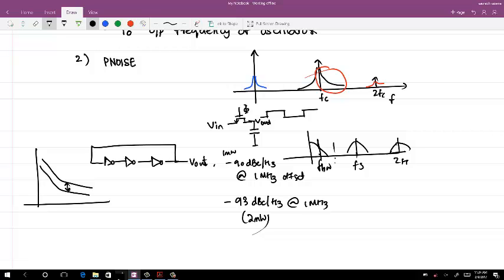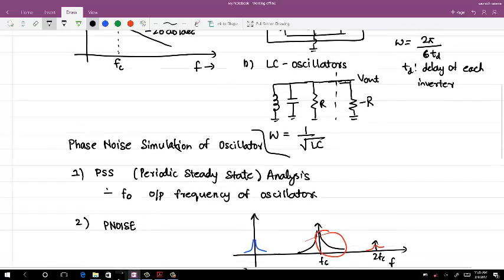Connect two in parallel. That is the easiest way. You can double the power and you can get the same frequency. So it's like I just copy that oscillator and connect node to node. This is actually connecting two in parallel. If you do that, you can maintain the scalability. Means other than the layout parasitics things change, but other than that, the scalability will be there for sure. Okay. Any questions?